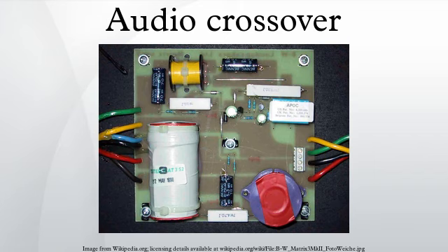On the other hand, if the audio crossover separates the audio bands in a loudspeaker, there is no requirement for mathematically ideal characteristics within the crossover itself, as the frequency and phase response of the loudspeaker drivers within their mountings will eclipse the results. Satisfactory output of the complete system, comprising the audio crossover and the loudspeaker drivers in their enclosure, is the design goal. Such a goal is often achieved using non-ideal, asymmetric crossover filter characteristics. Many different crossover types are used in audio, but they generally belong to one of the following classes.